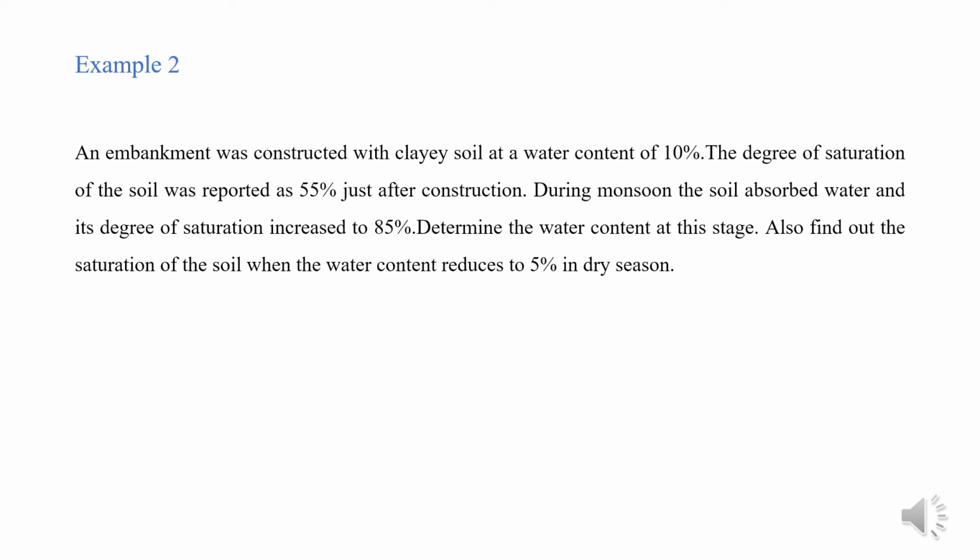So what is our given, right? Given is our water content w equal to 10%, and the degree of saturation is equal to 55% at this stage after construction. So from this, let us find out the void ratio of the sample. Okay, so let's recall the relationship wG equal to Se.